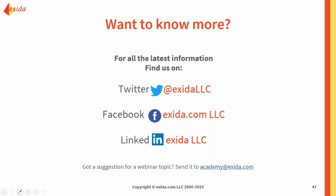I call SIL 4 a unicorn. Everybody said they've seen it, but has anyone really seen it? And as I said, there could be SIL 4s in nuclear or rail instances. However, when we're talking about the process industry, if someone comes to us and says, we want a SIL 4 SIF design, we go back and say, we need to look at the hazard analysis, we need to look at the LOPAs, the PHAs, how is this found? Because SIL 4 is not necessarily the right answer. We go back and have them look at a redesign.